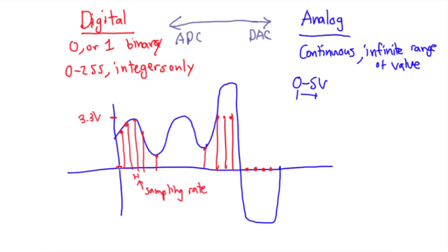And the idea behind that is that there's a set number of tick marks in here that the analog to digital converter can become. So say, for instance, this is one tick mark, another tick mark, and there are these set small values that it can only become. So it can only become this, it can only become this. It can't be anything in between these two little tick marks. And that's called the bit depth of the ADC. Bit depth. And in our case, it's 16-bit.